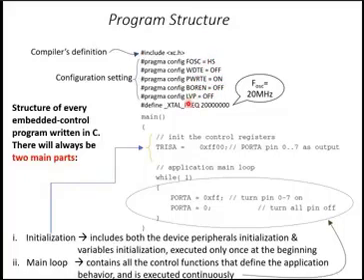For here, you define the microcontroller oscillator to be HS. Then you disable the watchdog, and you enable the power-up timer, and then brown out you disable. This code needs to be included. You need to refer to the previous lecture. For simulation, some of the coding lines need to be excluded. But for actual hardware, we need to include everything here.